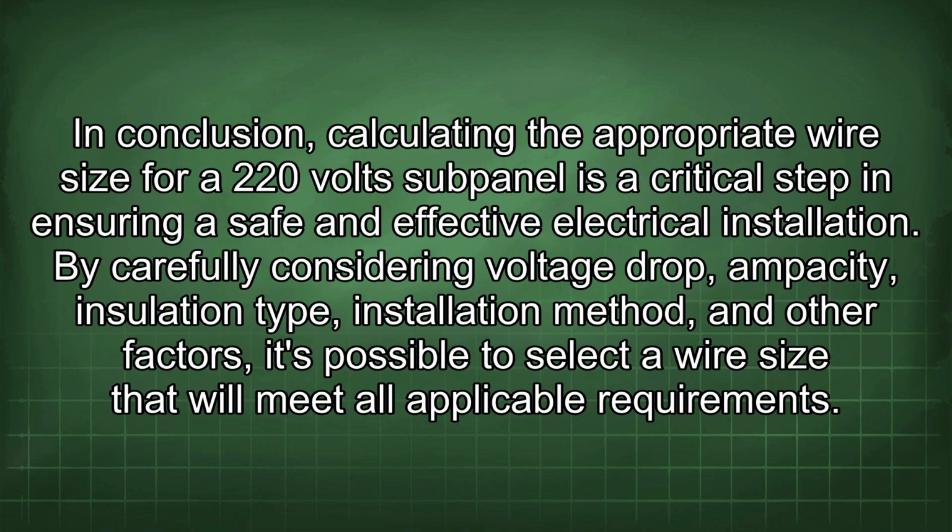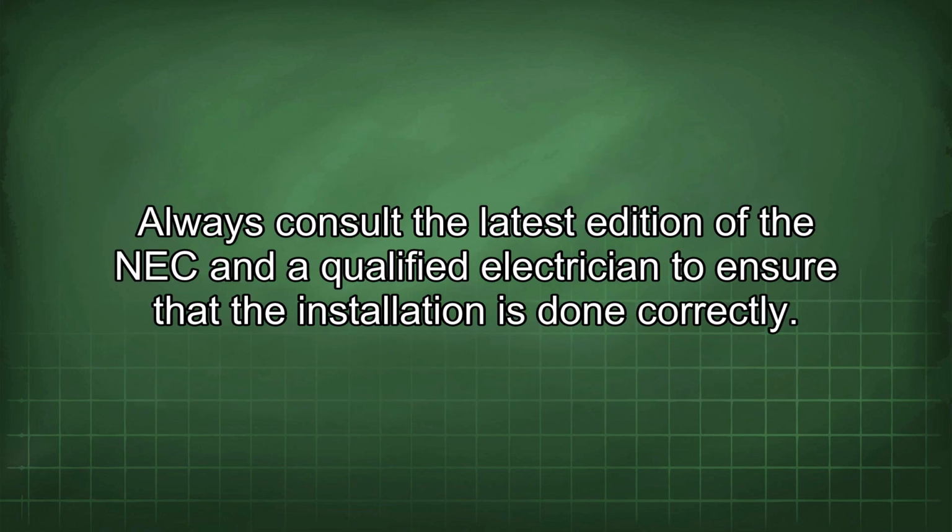In conclusion, calculating the appropriate wire size for a 220-volt subpanel is a critical step in ensuring a safe and effective electrical installation. By carefully considering voltage drop, ampacity, insulation type, installation method, and other factors, it's possible to select a wire size that will meet all applicable requirements. Always consult the latest edition of the NEC and a qualified electrician to ensure that the installation is done correctly.